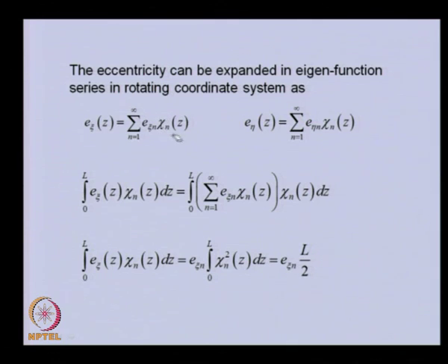So, it will depend upon what kind of rotor is there and what kind of boundary condition is there. We can get the eigenfunction from that, and this is some constant which will determine which mode will be contributing how much, and theoretically it will have infinite terms, because a continuous rotor can have infinite number of eigenfunctions.